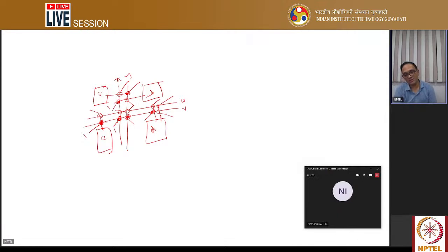If you make this bit 1, then this connection will happen. For a different design, you make another bit 1, then a different connection will happen. This is the reconfiguration of the connections. Similarly, the boxes that I've drawn, A, B, C, D, are also reconfigurable, right? Inside them there are CLBs, okay? Which effectively has a memory, okay?